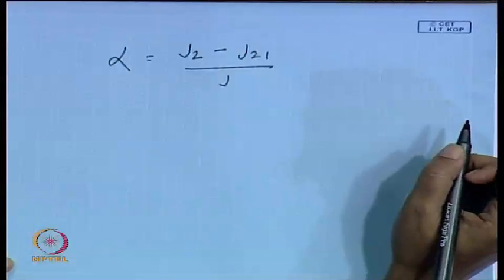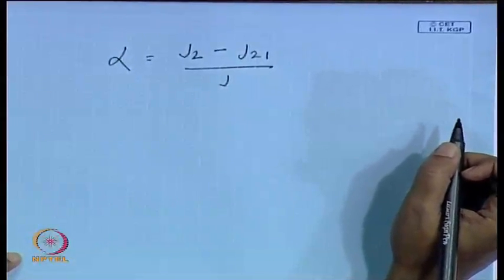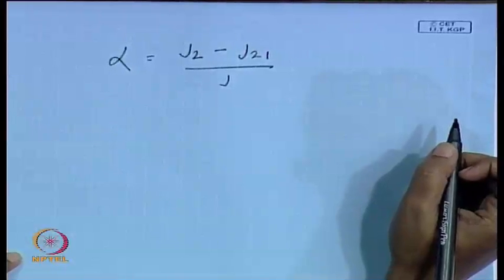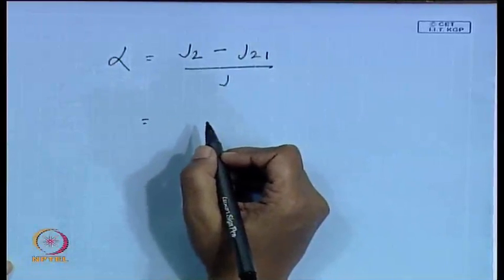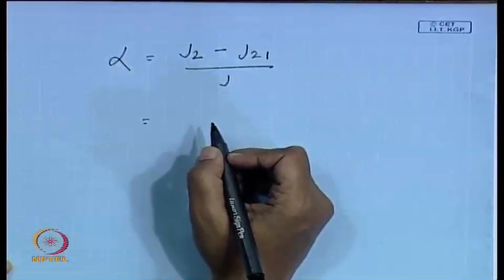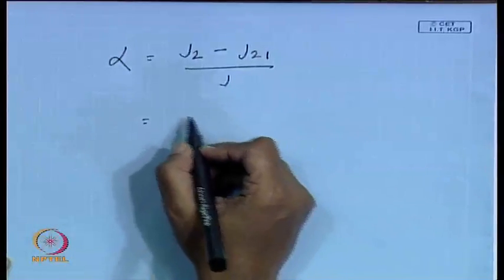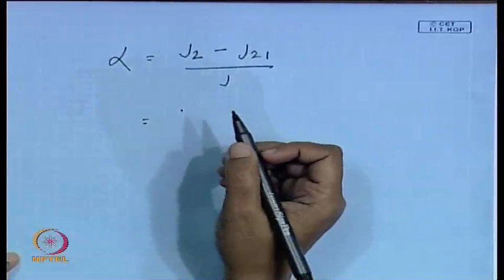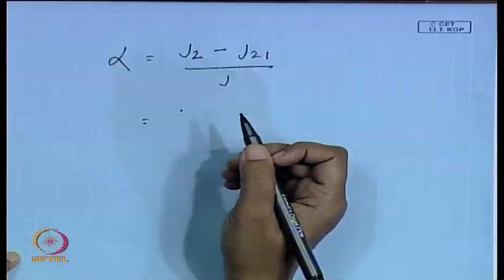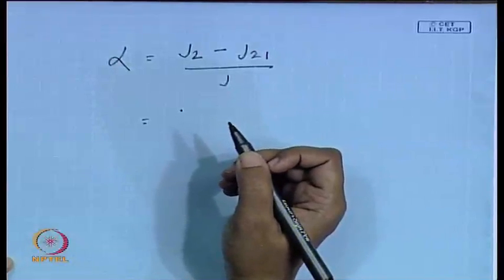For homogeneous flow, alpha equals beta. How can we express the homogeneous value of alpha obtained from the homogeneous flow theory? Yes, it is just the input flow rate of phase 2 divided by the total input flow rate, is it not?